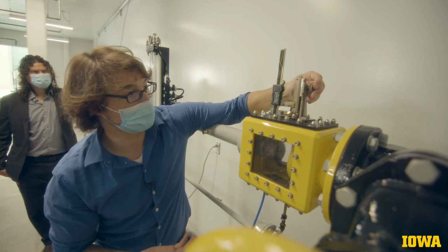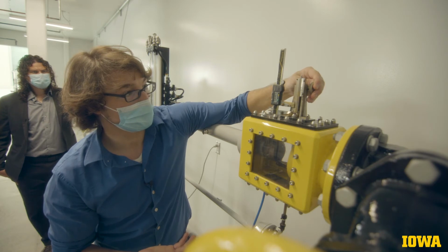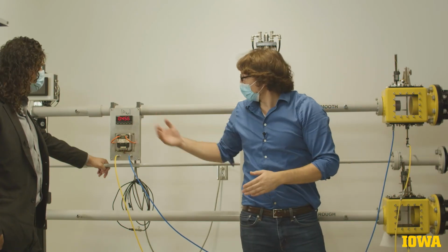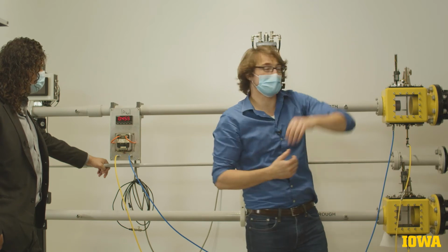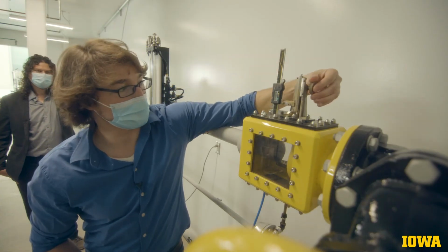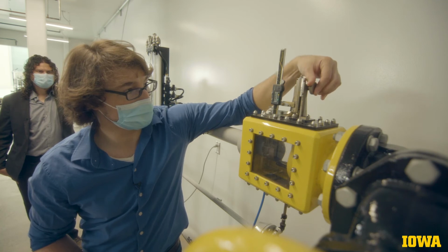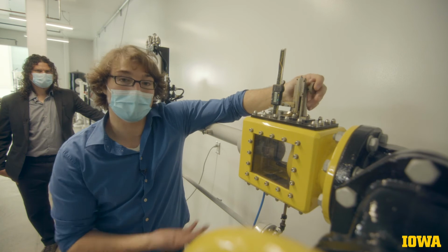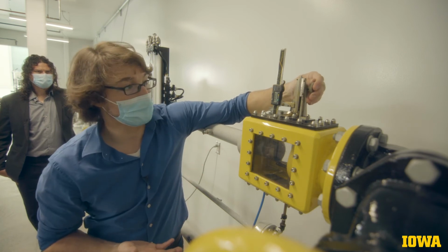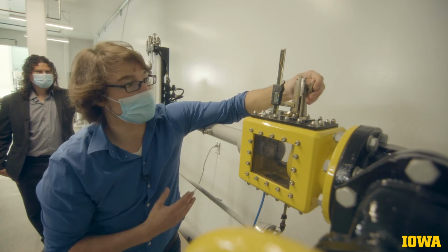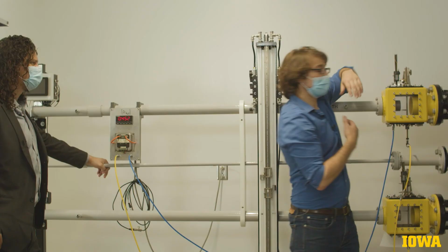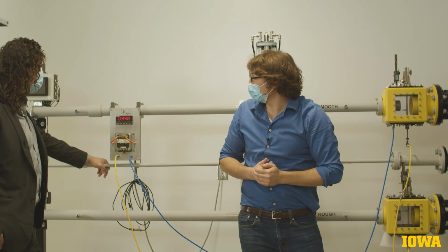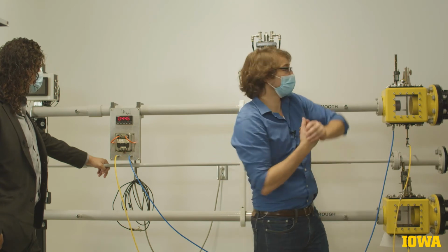So at 24 millimeters, 0.456. Resetting the probe's position, we expect that there may be some variability in where we place the probe, as well as in the actual process of the fluid moving through the pipe that would cause us to get a slightly different measurement, 0.445.